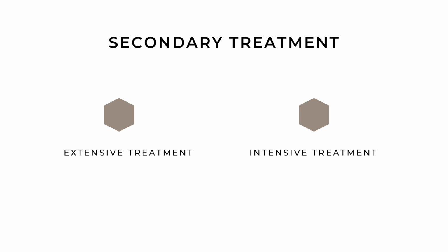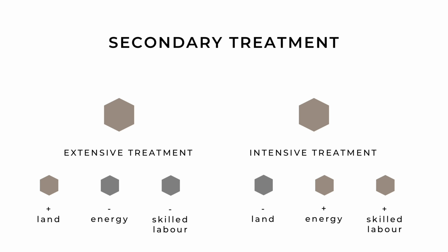Different technologies offer these conditions for the microorganisms. Some of them are extensive and others are intensive. Extensive treatment options require more land but less energy and skilled labor, while intensive technologies require less land but more energy and skilled labor.